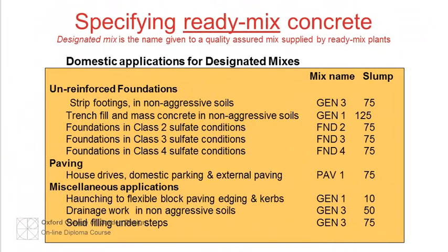If concrete is being used in sufficient quantity, the use of ready-mix is the best quality control measure and is the obvious choice. Its quality is guaranteed by the supplier in writing. If it is not possible to use ready-mix because of access difficulties or the small amounts required, then reliance has to be placed on a responsible and knowledgeable contractor who will have to work to nominal mix proportions.